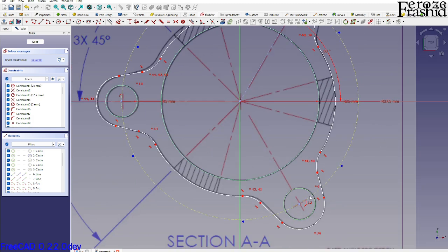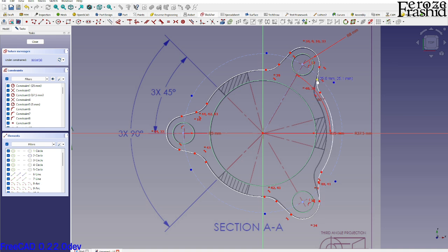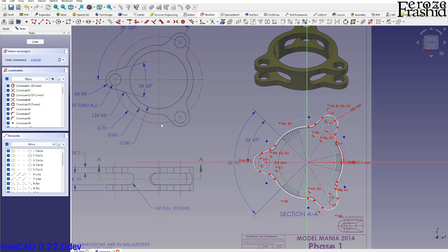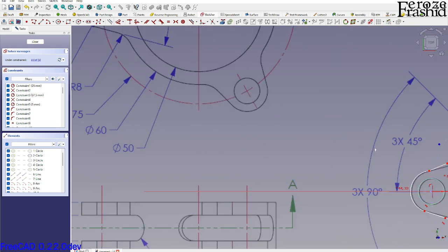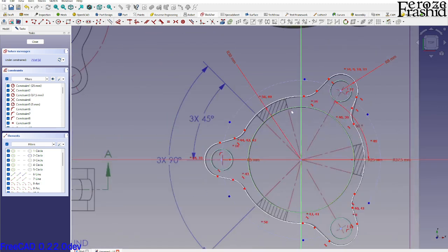and there. Okay, we have 10 degrees of freedom, maybe 3 degrees of freedom times 3, so 4 degrees of freedom actually. Okay, so this is moving erratically, so we want to go and make all these 3 equal, and then see that one is radius 30, so put some value on there that will actually constrain it, so it's less moving now. Now we have 7 degrees of freedom, and I know what it is.